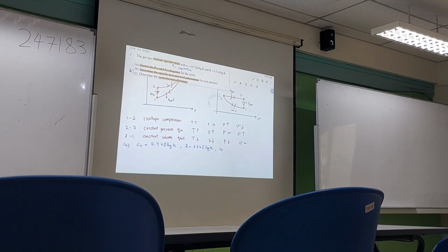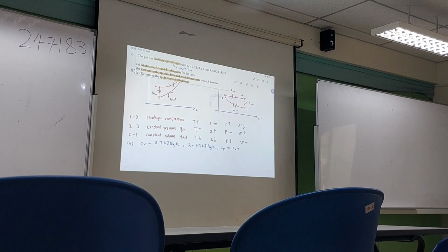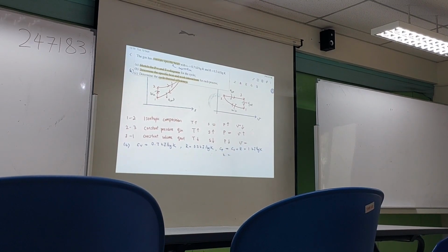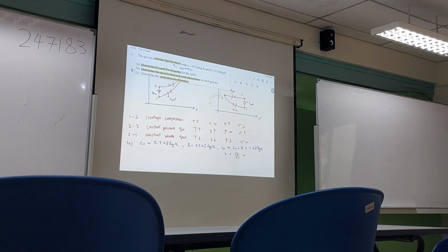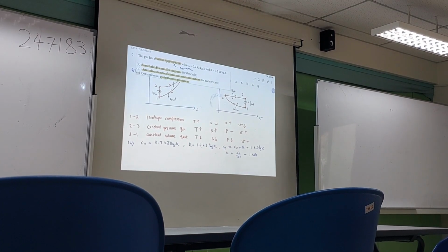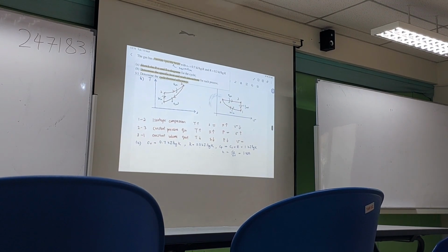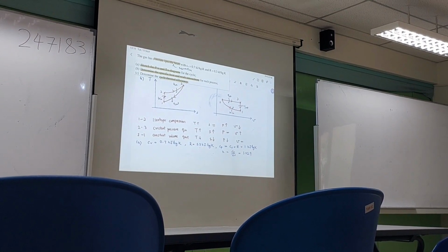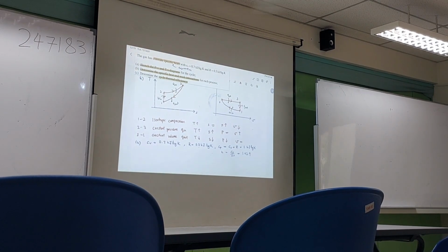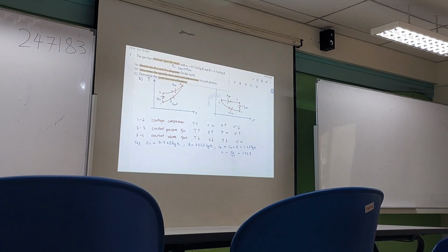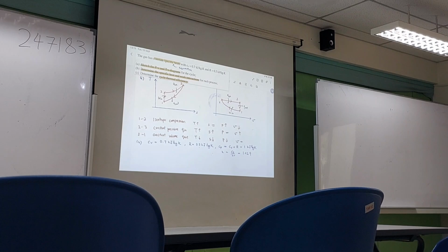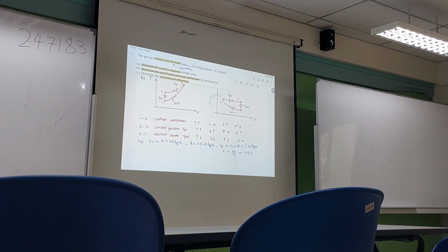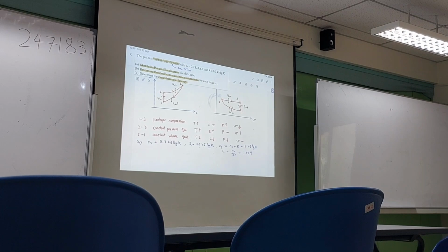Based on this, you can also calculate Cp, whereby Cv plus R is equal to Cp, so here Cp is just 1. K is Cp over Cv, and this will give you 1.429. You can see the value here is not quite the same as the one in your table. This K is the same as the gamma that you use in applied fluid. This one is the same thing, just different. I mentioned this a few times. Okay, now we move on to analyzing the specific heat and work interaction for each process.